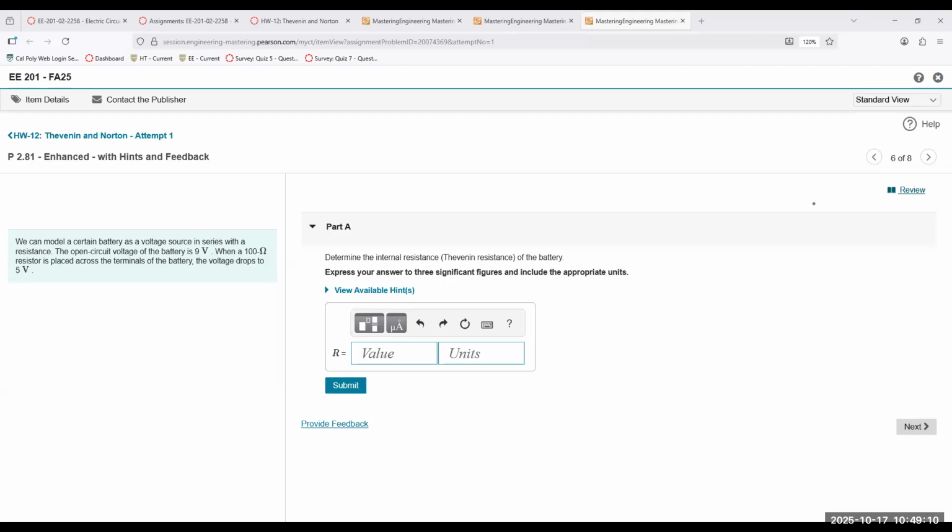So first you measure IN. When you measure current on a meter, what do you have to do? On the meter, you have to take the terminal and switch it manually to the current measurement terminal. So you get that done first. Well, for Norton, what do we need? We need a short circuit wire going from A to B. A meter in current measurement mode is a short circuit wire. So the meter provides a pathway for the current to flow as well as doing the measurement. Keep this in mind when you're doing the lab. You connect the meter, put it in current measurement mode, turn the power supply on. Whatever current is going through, that's your Norton current.